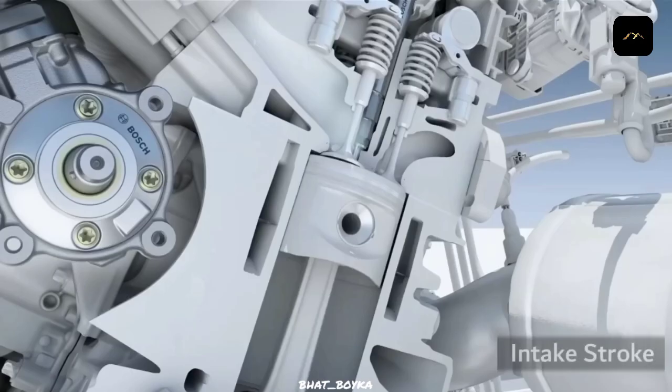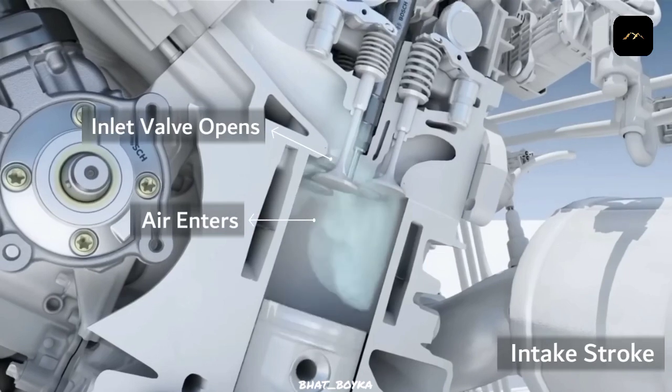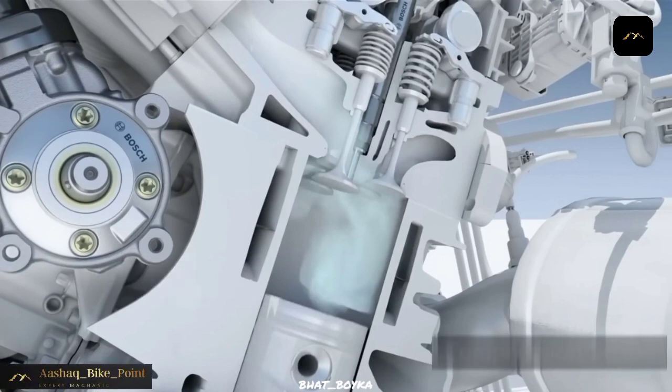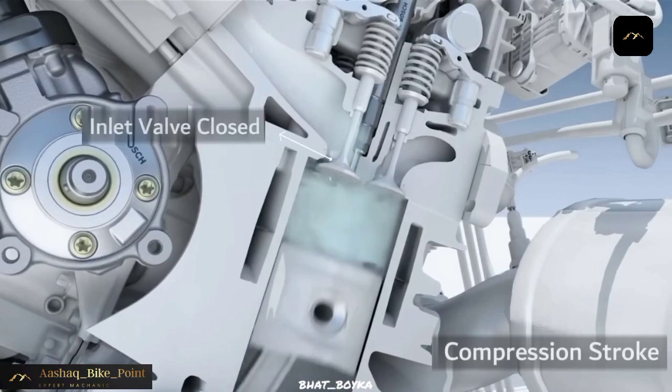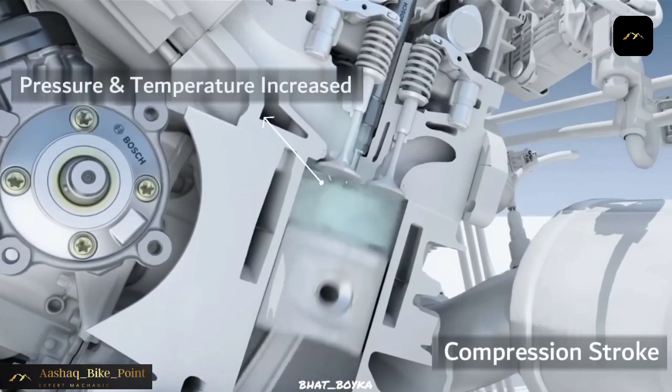Intake stroke. In the intake stroke, the piston moves down, the inlet valve is open, that allows air to enter the cylinder and fills the space. Then the piston reaches the bottom center and again starts moving up. Compression stroke. The piston starts moving up, the inlet valve is closed, then the air is compressed. The pressure and temperature of the air increase due to compression.